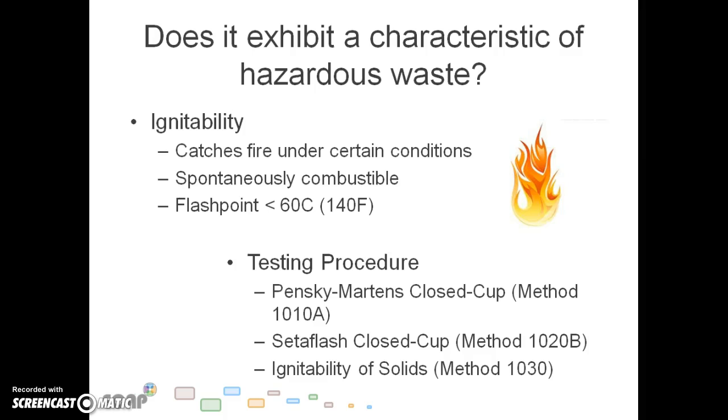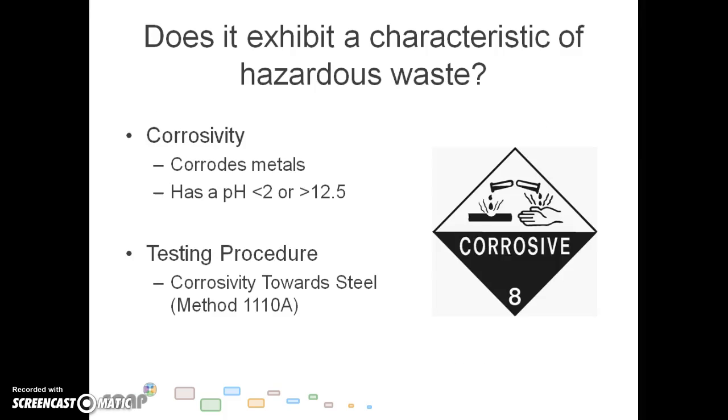An ignitable waste, which will catch fire under certain conditions, is spontaneously combustible or has a flash point of less than 60 degrees C or 140 degrees Fahrenheit. Wastes that are typically ignitable include paints, degreasers, and solvents. Test methods that may be used to determine ignitability include the Pensky-Martens closed cup or the Setaflash closed cup, and the ignitability of solids methods.